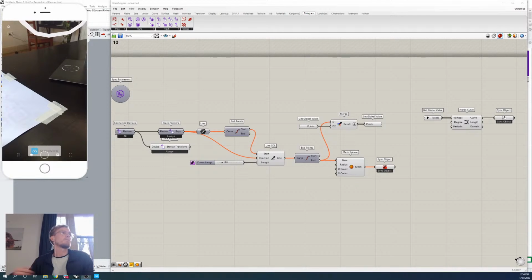If you're getting the input parameter v failed to collect data error, that's because you haven't actually gone onto your device and tried to draw a curve. So once you have this setup working and you're sending all of these global points into this component, the points will go ahead and input into here. Basically, by default, you won't have any points coming in with that global variable there straight away.